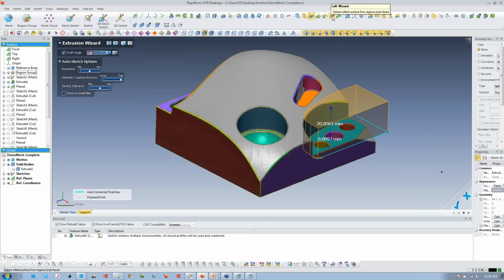In order to successfully complete a quick modeling command, you'll have to have the basic information needed to define an extrusion, which would be where does it start, where does it finish, and what are the bounds. So some sides and a top and a bottom. And similarly for a revolution or a sweep, we'll have to have a profile and a path and an axis. Does that help?